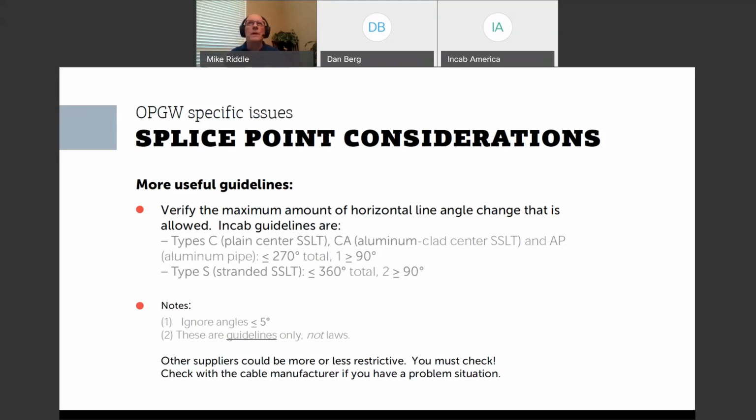So if the cable's RBS is 10,000 pounds, it's a center tube design, and I tell you the zero fiber strain margin is 50%, you know that when the tension is above 5,000 pounds, the fiber has some tension on it. Now you try to keep that strain on the fiber below 0.2%. That's sort of the optimal limit published by fiber suppliers.